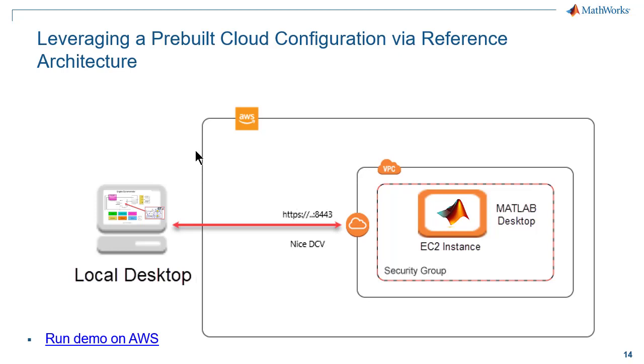remote desktop. And then what this allows me to do is take my model order reduction simulation setup from my local desktop machine, and then transfer it to the machine on the cloud that I can then use to speed up my simulation runs. I chose a machine with 32 physical cores, which in my case worked really well. There's a ton of different machine types available, so you can select the one that's best suited for your particular needs. This approach supports all the major cloud service providers like AWS and Azure. So let's take a look at what this actually looks like.